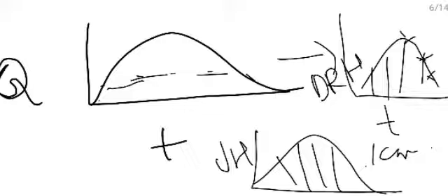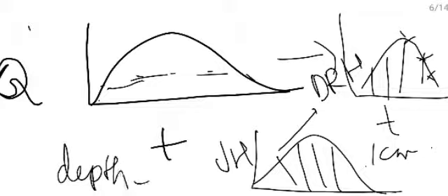So to obtain the flood hydrograph for a particular year, you have to first take this unit hydrograph, then multiply each coordinate with the effective depth given by the meteorological department. Now this depth should be what? This depth should be taken after subtracting.